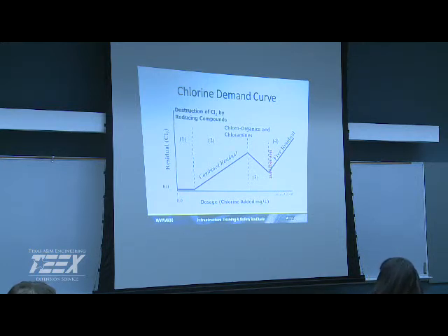And then you get into phase 3, and we actually have a decrease. And so when you start to have a lot of taste and odor issues, people say, man, it really tastes like chlorine, like a swimming pool, you're probably in your area of number 3. And the way you tell that is boost up your chlorine a little bit, and your residual's going to drop.